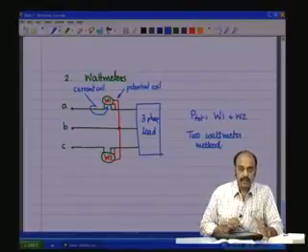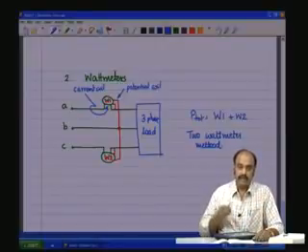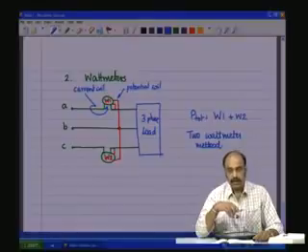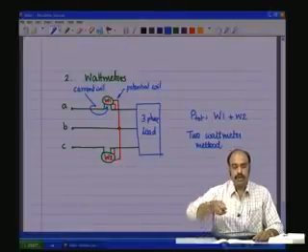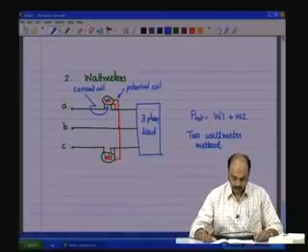So, if there is a center 0 wattmeter, then you can take the readings easily. Otherwise, if it is just a one-direction wattmeter, you will have to reverse the direction if it goes negative, when the power factor is pretty low.